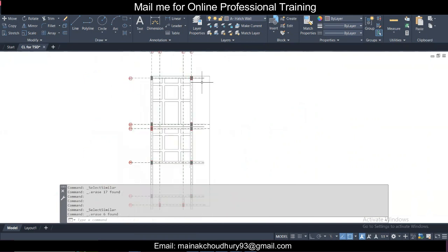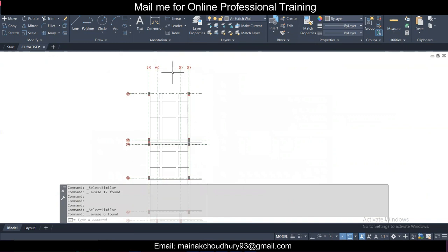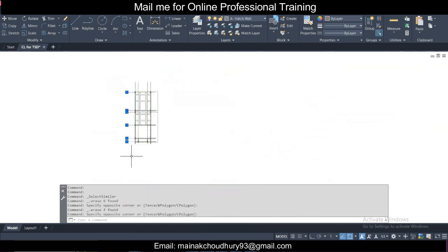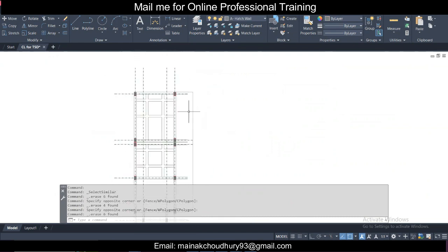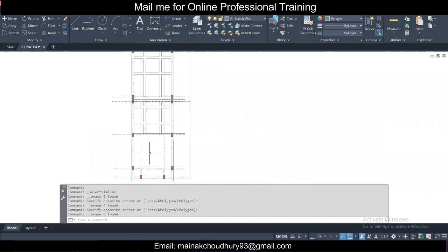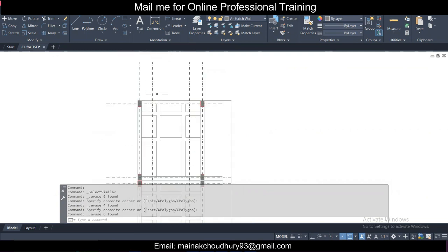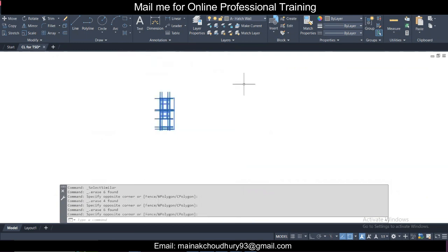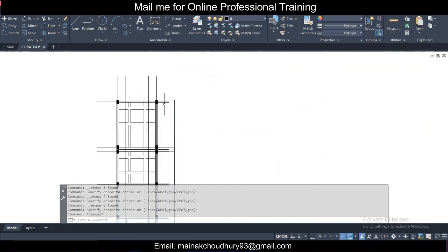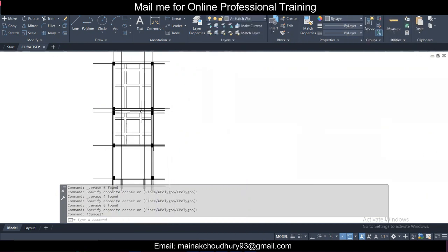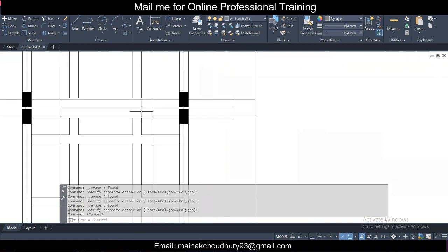And here, the center lines, whichever we need to give, let's give. ABCD we don't need right now; Tekla will give the ABCD whatever is required. So these are all the column center lines. You need the center lines for the beams as well. First of all, I'm putting everything in the zero layer. There are a lot of layers because this is an architectural plan, but if you take this many layers into Tekla, it will create problems.